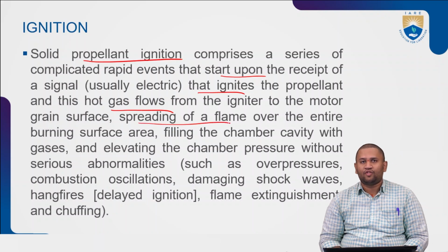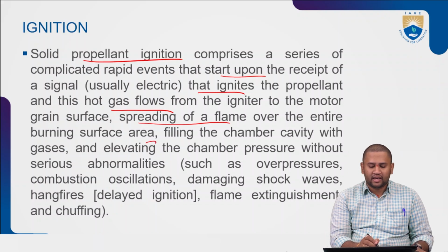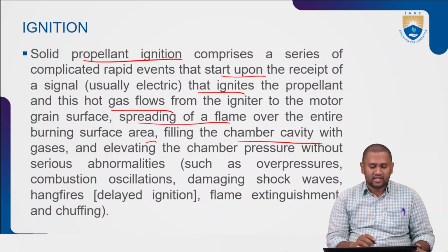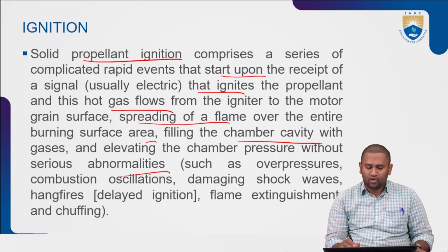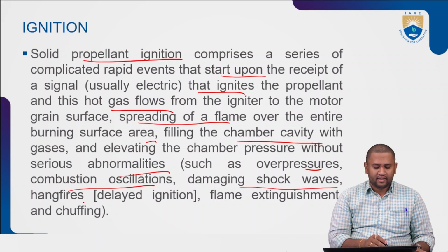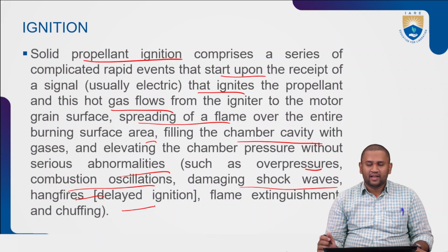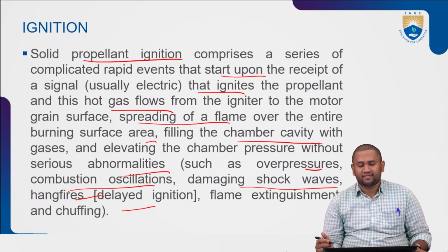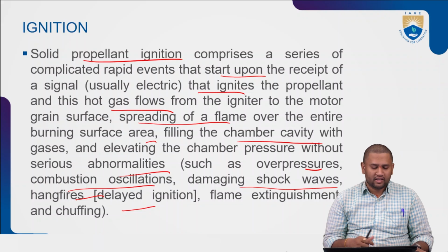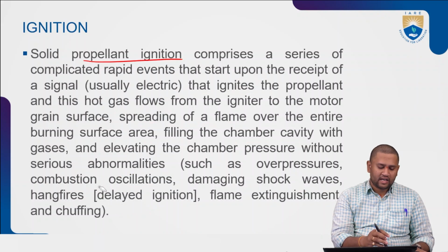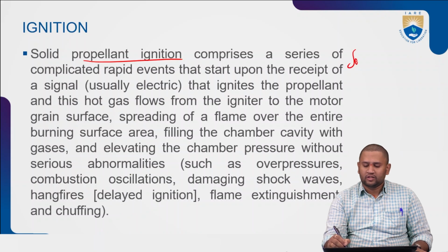It involves spreading of a flame over the entire burning surface area, filling the chamber cavity with gases and elevating the chamber pressure without serious abnormalities such as overpressures, combustion oscillations, damaging shock waves or hang fires, which means a delayed ignition, flame extinguishment, or chuffing. We'll undergo this.